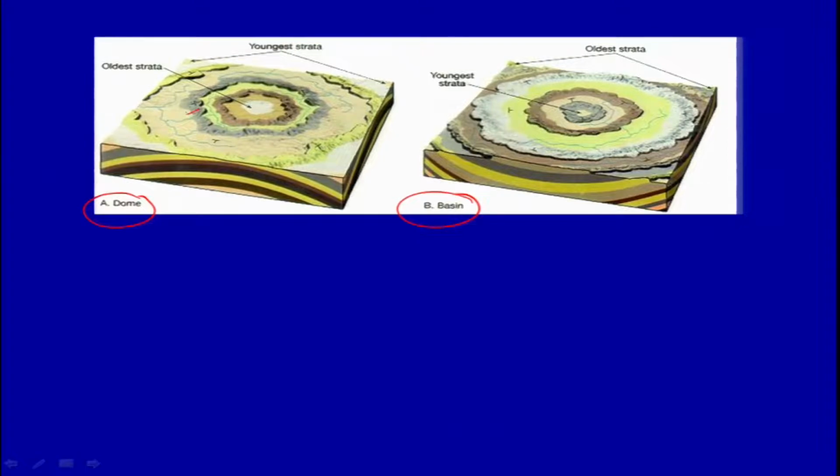These are dipping in this direction here, this is also away, this is also like this. So they are dipping away from one another. Whereas here they are dipping this side, and this one is dipping this side, dipping towards each other. Hence this is a syncline and this is an anticline.